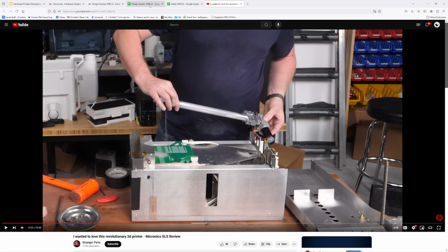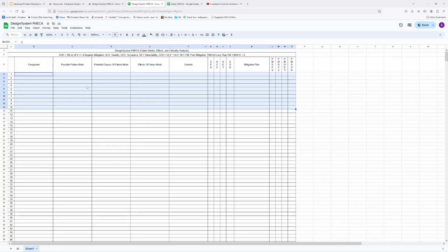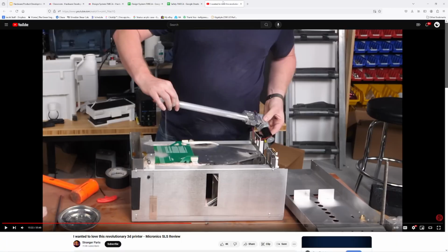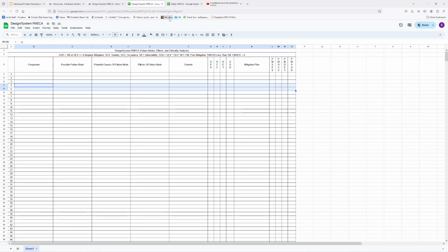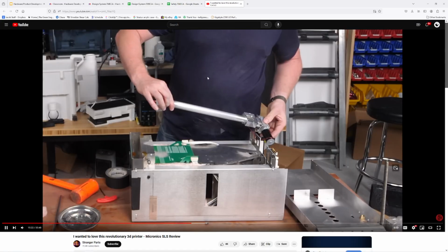This stuff, it's not powdered steel, but it can still get into gears and cause damage. So where is that in the design FMEA? How do we prevent that from happening? Do we have any sort of wipers to keep it out? Is there some sort of procedure to go in and clean it up automatically? Or do you need customer intervention? What's involved with the customer intervention? What are the hazards for the customer intervention? Does this design FMEA now cause a safety issue?